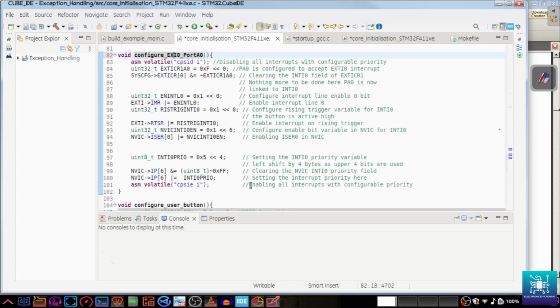So we do EXTI0 port A0. So this is the actual configuring of the external interrupt for port A0. So we have configured the port now. So that is one step, because the port has to be woken up and configured physically. That is the physical electrical configuration. So configure the port electrically, setting it up as an input port, and so on and so forth.